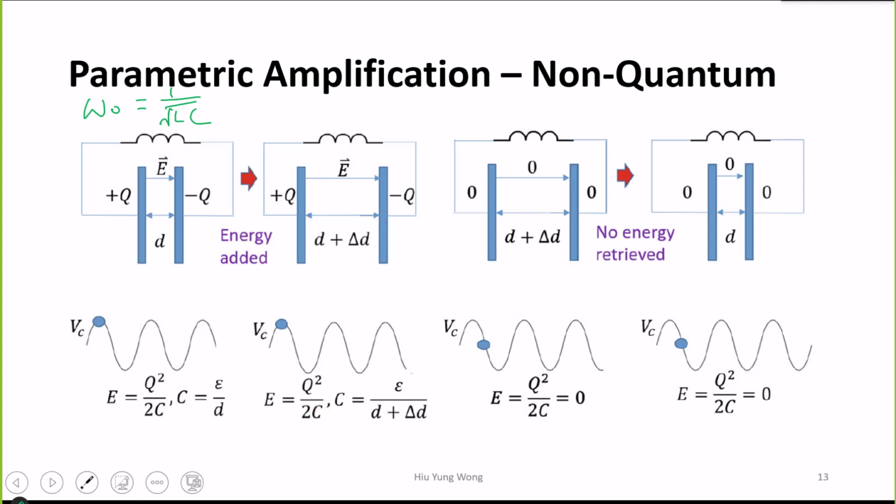But it's easy to understand because these two plates have an attractive force. When it moves, you are performing work on the system. So you are using mechanical energy and converting it to electrical energy, which makes a lot of sense. Once it's done, then you wait, because you now will convert everything to inductive energy because it's oscillating. So now you have a large current, but you don't have any charge across the capacitor. So there's no force, right? Now at this stage, you have 0 voltage.